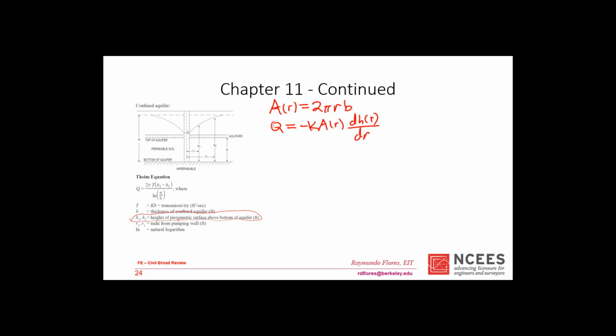The reason is that it's possible we only care about two spots, because maybe I can extract information about the flow and I don't need the entire thing. So it's possible to put two piezometers, one here and another here, get readings, and then find out what Q is in that section.